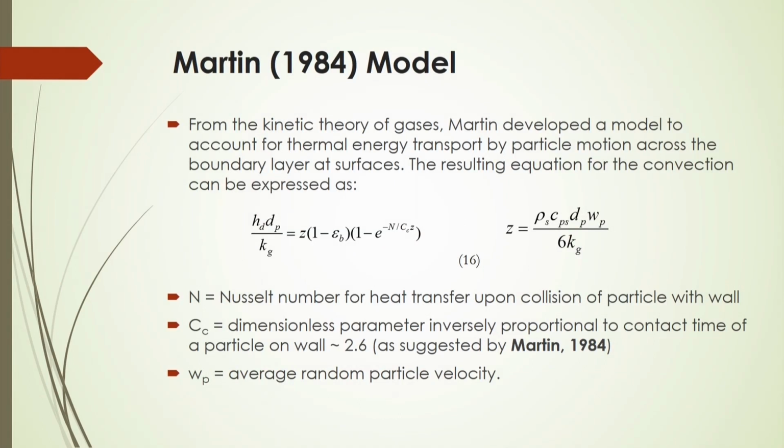Martin 1984 developed this equation to calculate the convective heat transfer coefficient in the dense bed medium based on the kinetic theory of gases, and Martin developed the model to account for thermal energy transport by particle motion across the boundary layer at the surface, and they developed this equation number 16 to calculate the heat transfer coefficient.